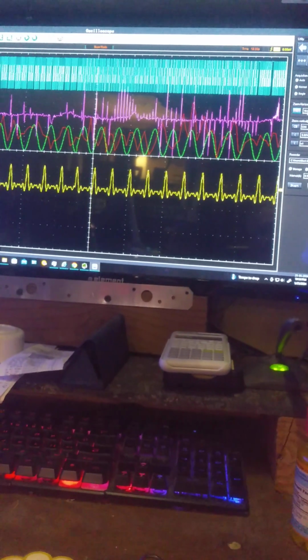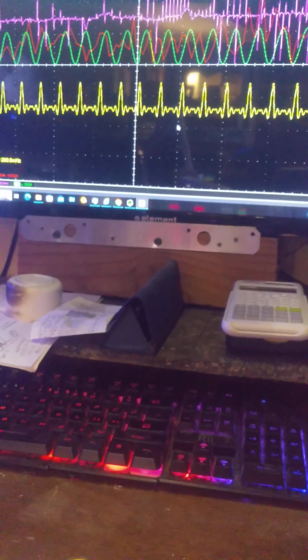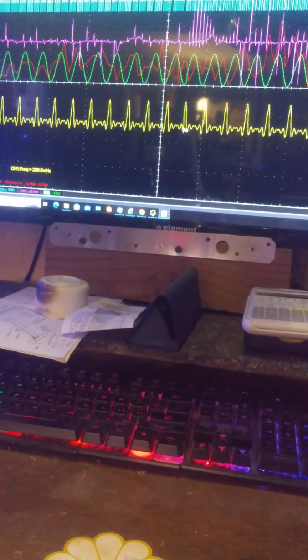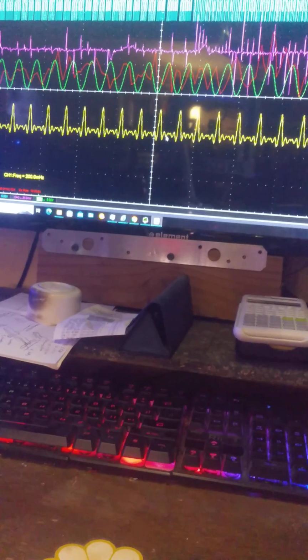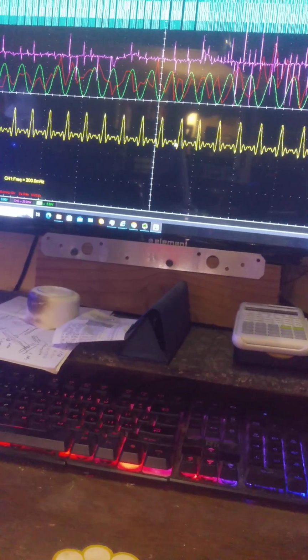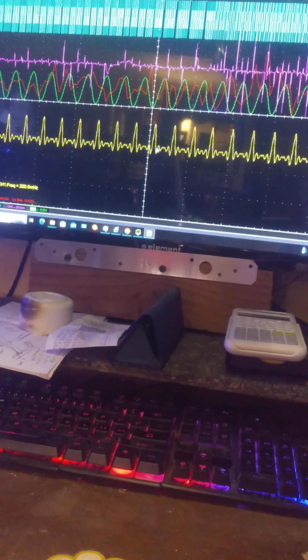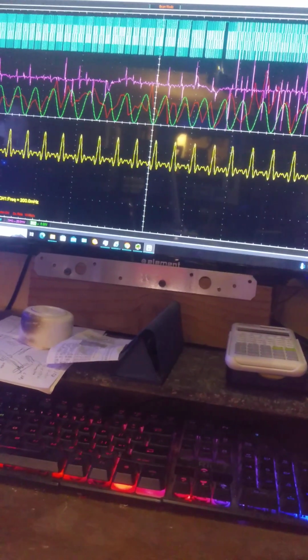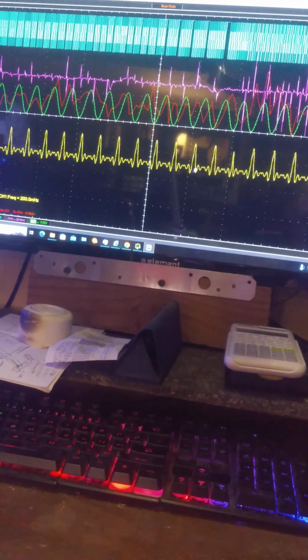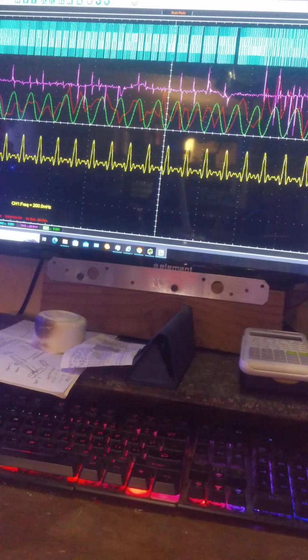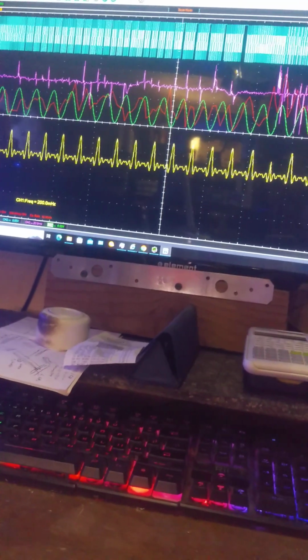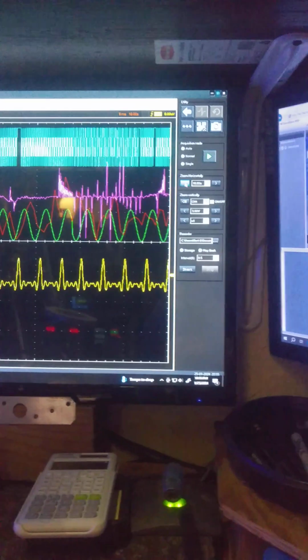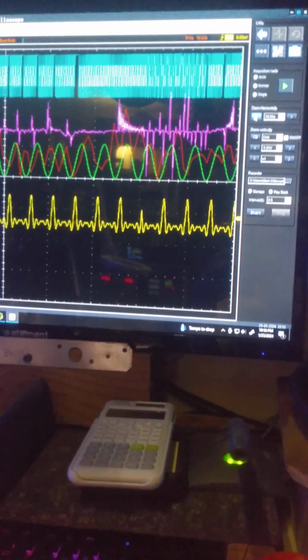Because again, this is set to 10 seconds per division, so the square here is like 10 seconds wide, so it's acting like there's less than about two pulses per 10 seconds, so like 5 seconds a signal. So a period of about 5 seconds. But let's see what happens as we adjust the frequency.